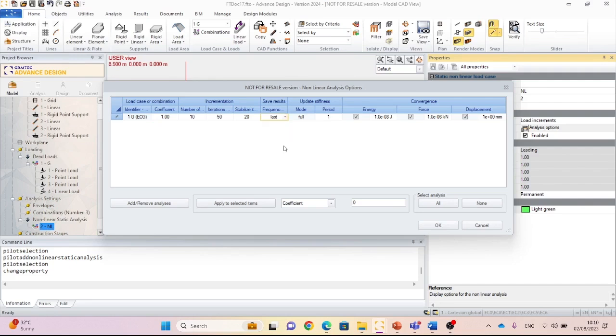So somebody can plot a P delta curve, for example, a force displacement curve, and see all the different stages of the equilibrium of this particular frame, and identify the different response throughout. And finally, there is the option to run a quasi-Newton or a full Newton-Raphson methodology